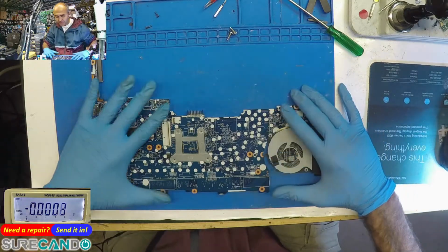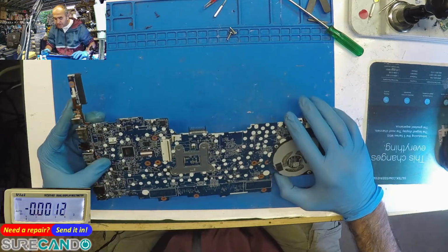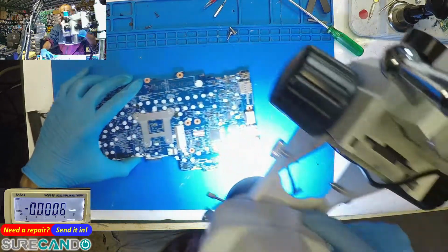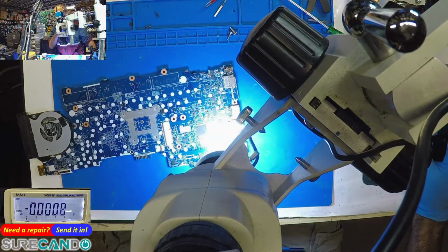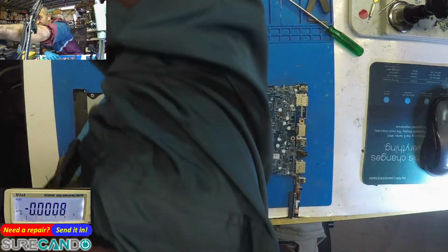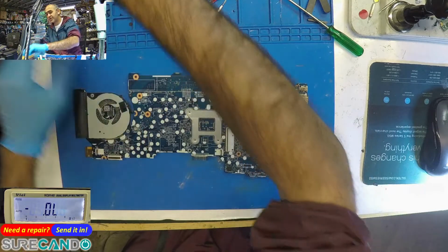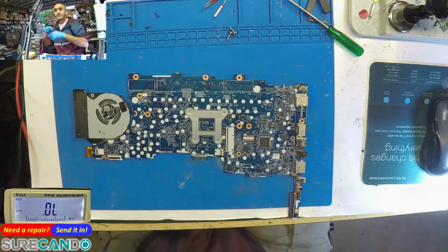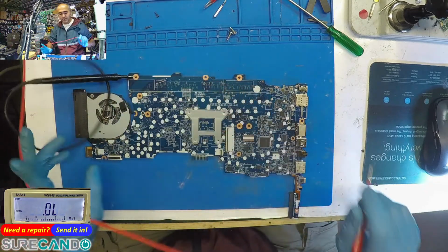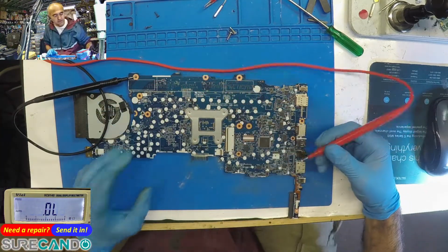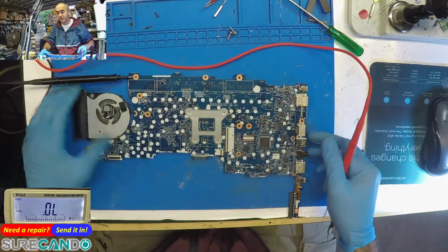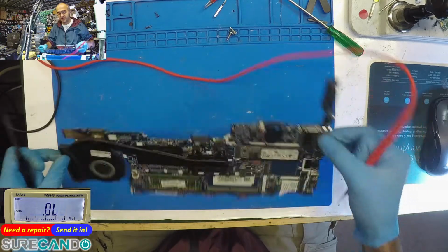Right, so we're back at this motherboard. Definitely there's a component playing up on this board, so it is currently not in a booting stage. Something's probably shorting something, right? So just have a quick look at resistance mode. You need to make a rule in our diagnostics that the multimeter is only for two reasons: diode mode and resistance mode, nothing else. Maybe occasional voltage checking.